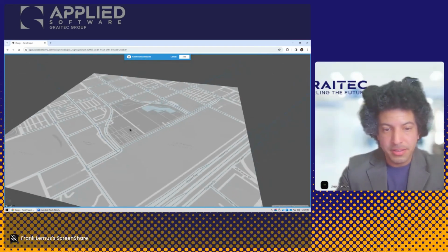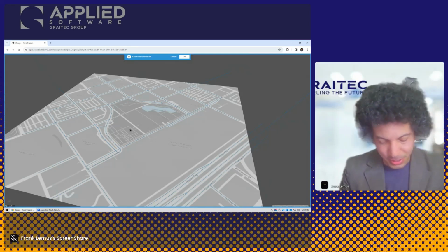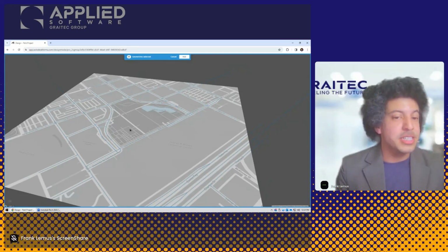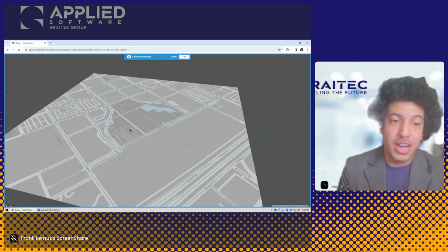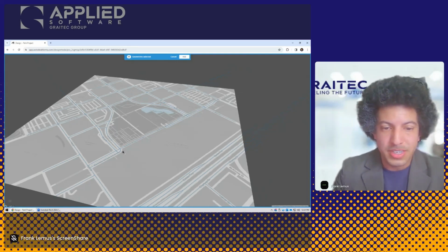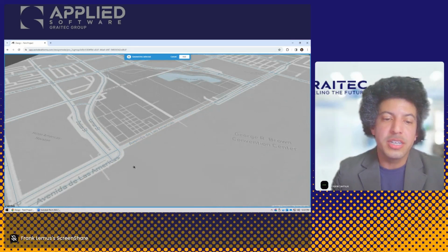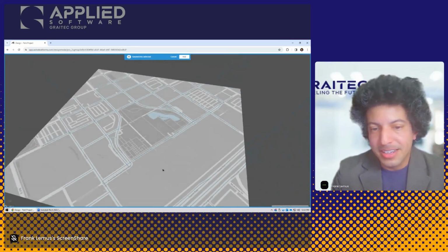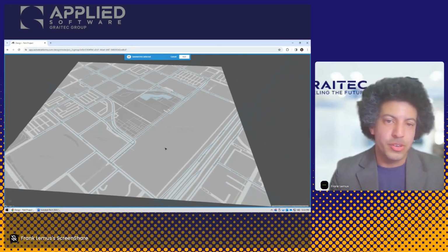If I hold down the Shift key, yes, I know I have a problem with that too because there we go again with Revit. In Revit, Shift means deselect, and Control means to add to your selection. Well, in Forma, you've got to get used to the opposite. Actually, there's just one button. It's just Shift. So if you hold down the Shift key, then you can add extra things, or if something is already selected, you can click on it to deselect it or click to add it. That may be one of the things that they might try to improve on, the user interface.